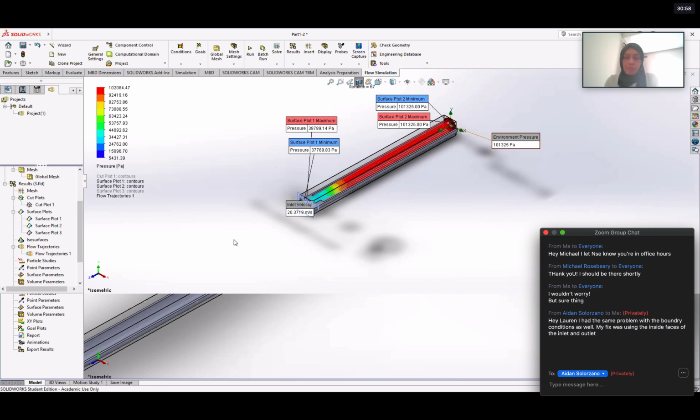The only thing that happens between 1 and 2 is a sudden expansion. The flow comes with a specific velocity, and accordingly it will have an inlet pressure that we don't know. It goes through the pipe. When the area changes suddenly, the sudden expansion makes vortices occur at the two edges that you see.